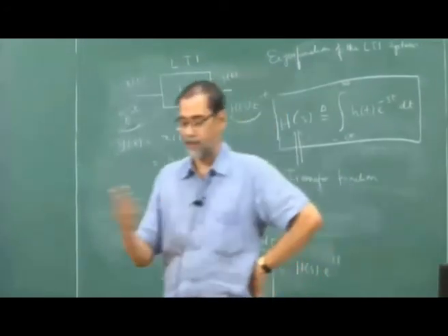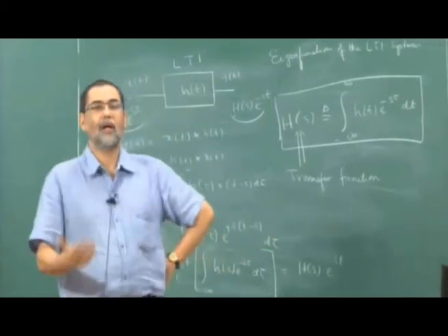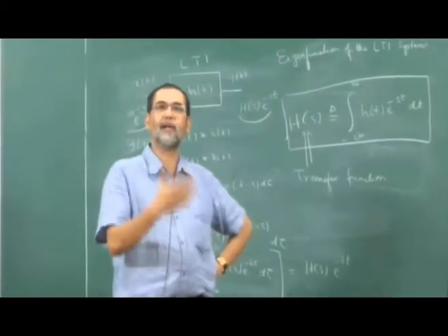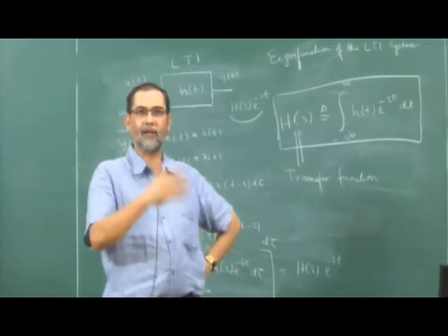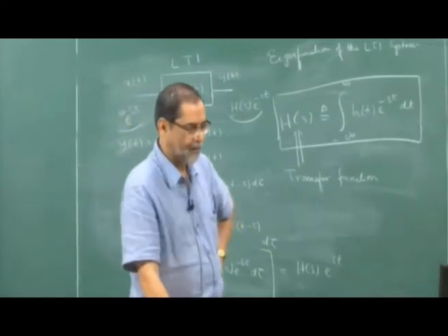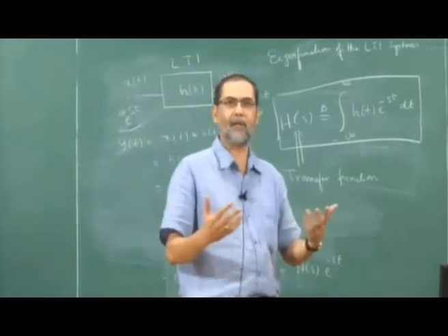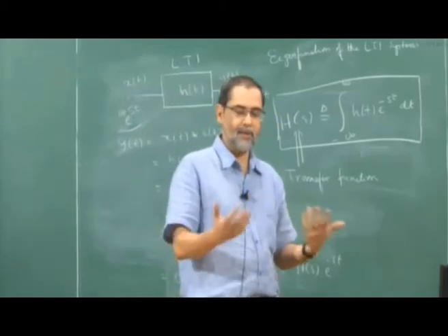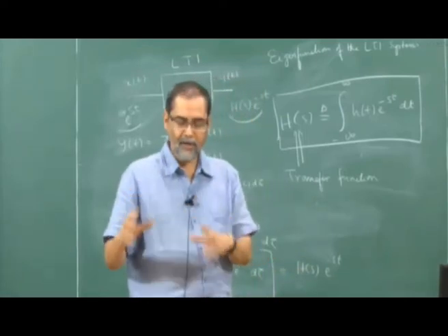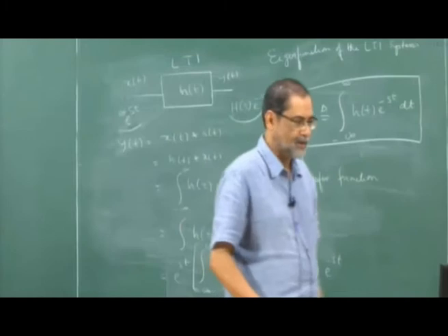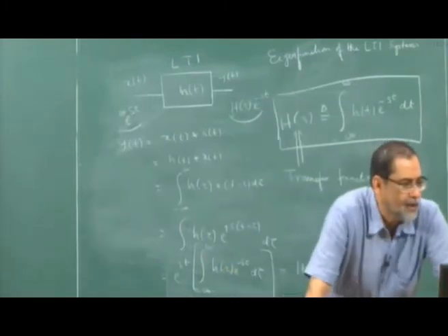In fact, there is an isomorphism between LTI systems and linear algebra theory. You can represent one in terms of the other, so there is a connection between the two. We use similar language: there we say eigenvalues and eigenvectors, here we say eigenfunctions. So the idea is very similar.